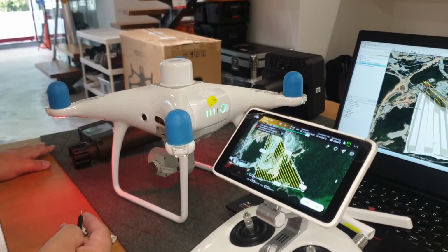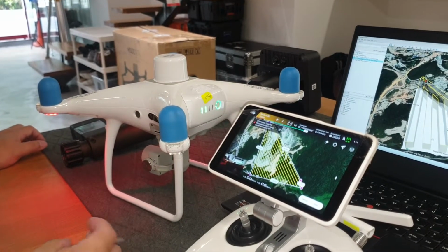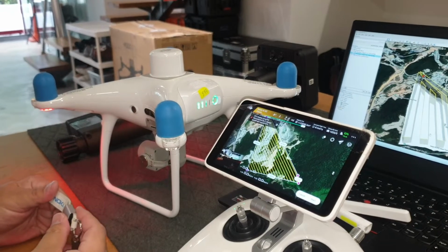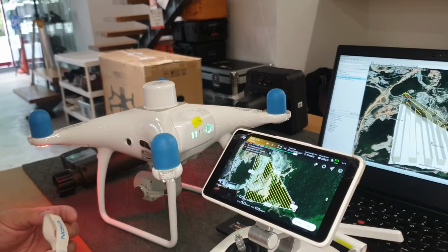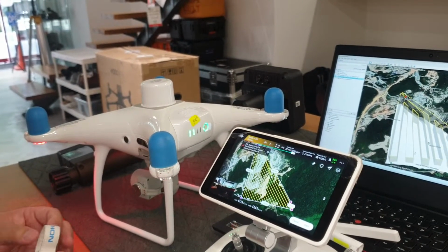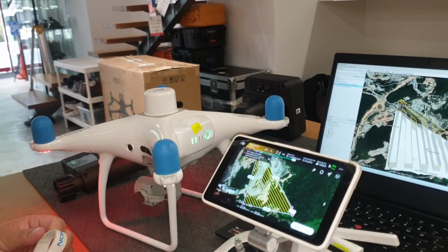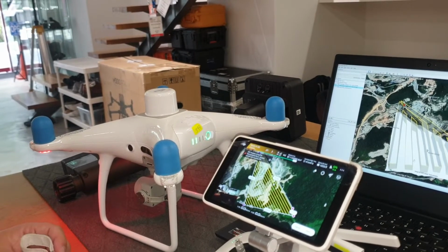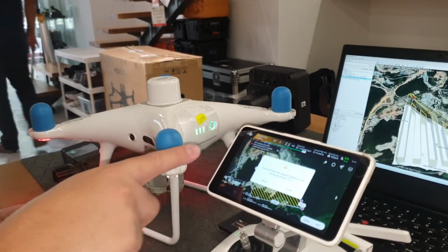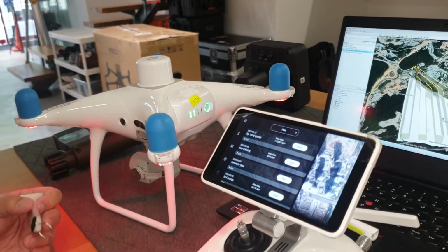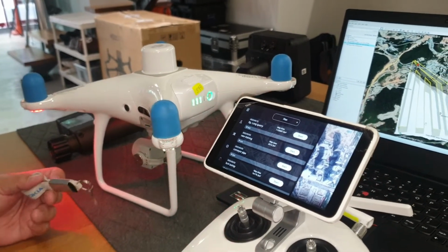Okay, so just thinking through the flight plan, as long as you've brought them out as polygons from Google Earth into the flight planner on here, put it in as a 2D photogrammetry, set the flight heights. I think the camera timer duration was on there as well, wasn't it? As part of that initial automatic setup. It's fully automatic, because it already knows, calculating based on the height and your speed, it will then work out the intervals, and the grid and the overlap as well.